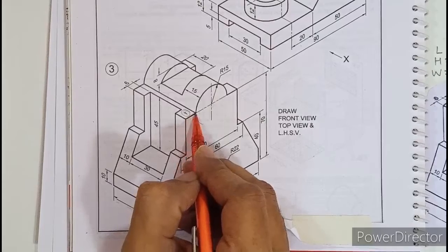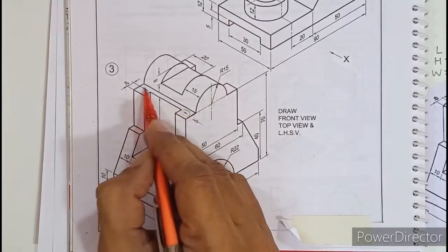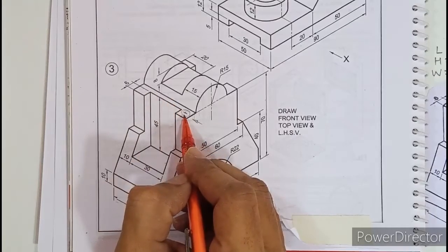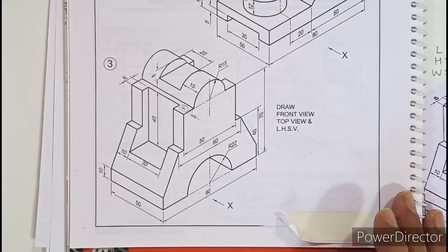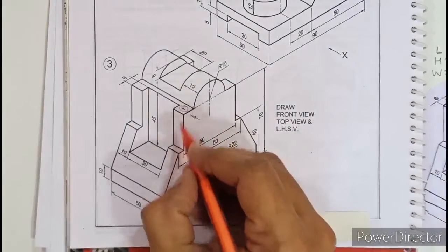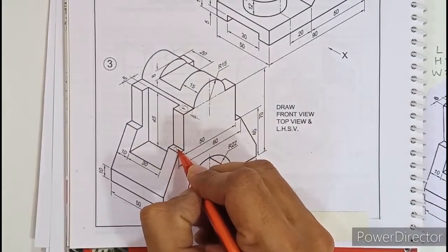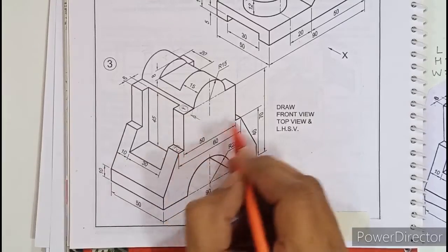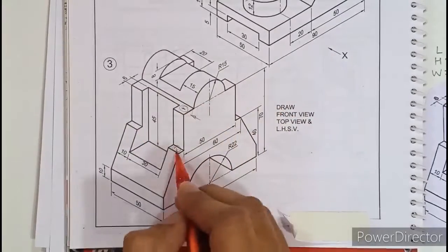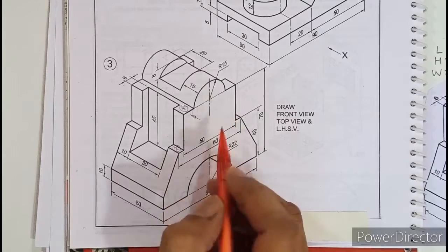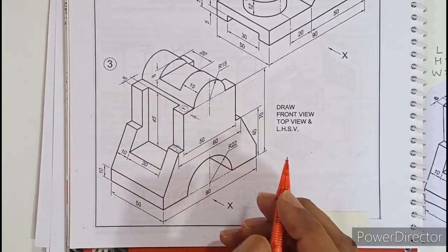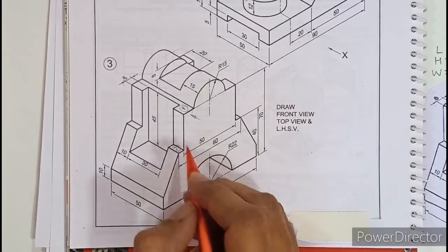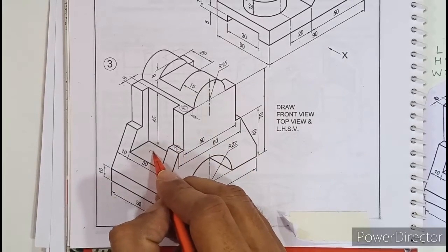So if you are successful in understanding where this line is drawn in the front view, you can easily draw this rectangle number 1. Apart from this rectangle number 1, can you see any more flat surfaces as you move down? See, below 1, there is a thin rectangle which is on all the 4 sides, first, second, third and fourth. So that is rectangle number 2. So first is this C type, second is this rectangle. Anything else? Any more flat surface? Yes, this one is the third surface.